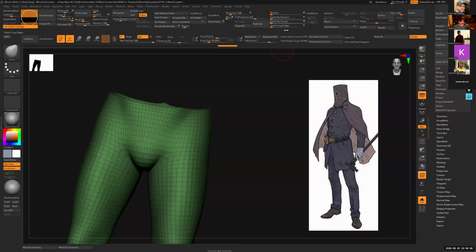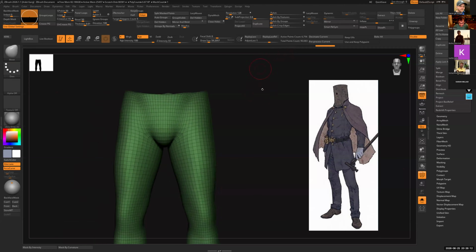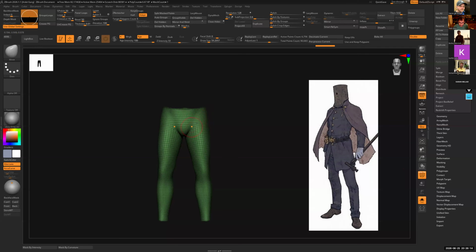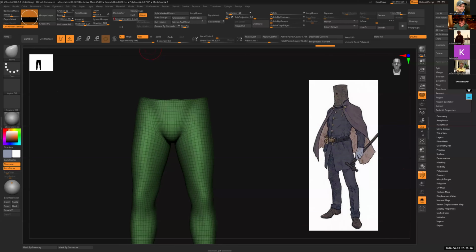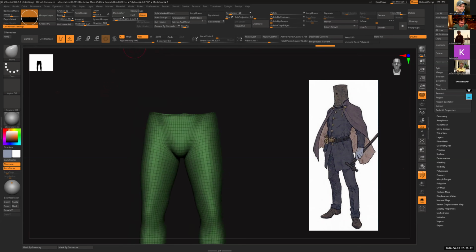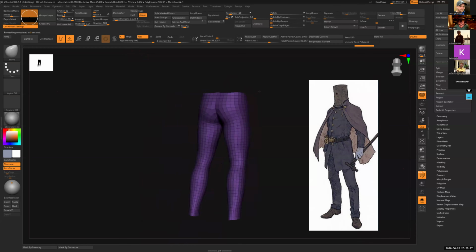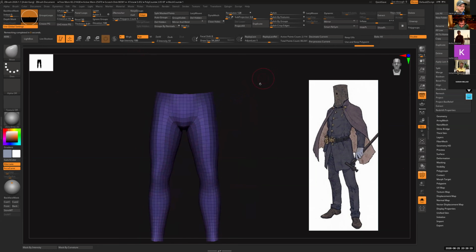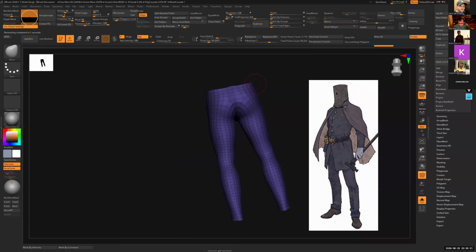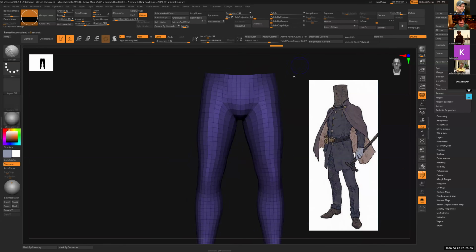I'm going to run a little bit of polish and polish the crisp edges as well. And I'll make sure I have symmetry turned on. I always start with keeping my poly count as 1. And then I do remesh. You can see the topology is actually pretty good already. You can hit ZRemesh once again to soften out the things.